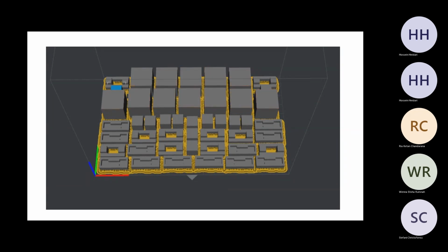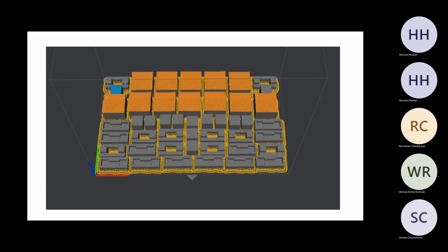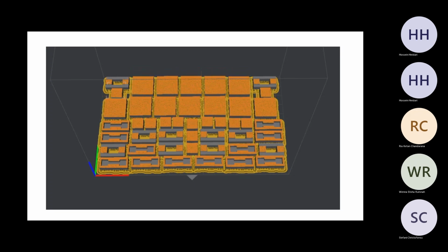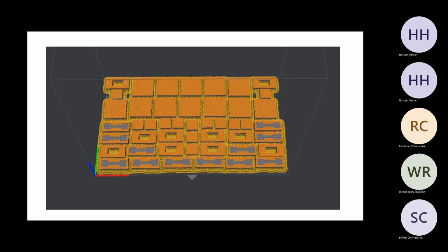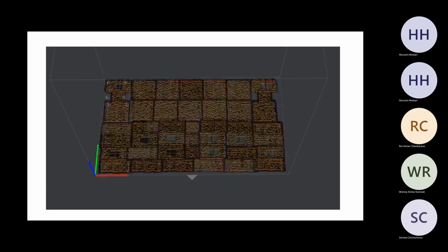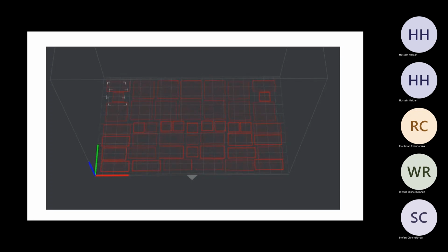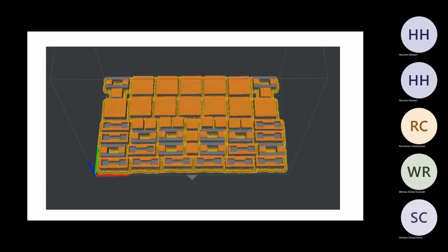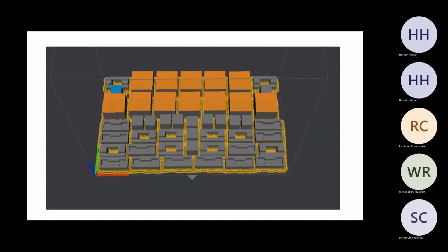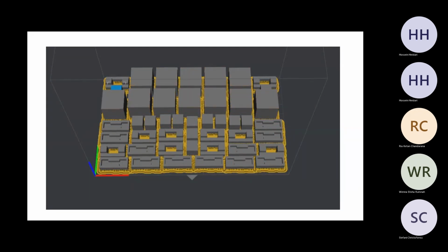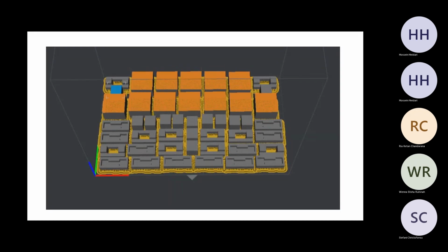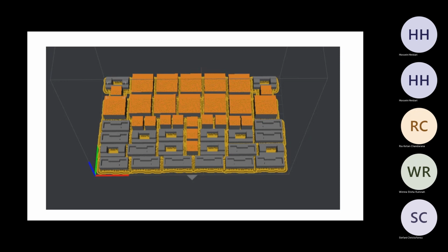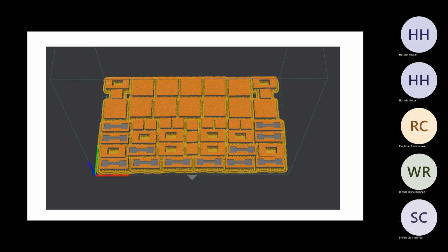Well, the thing is, do you guys know how these printers basically limit the penetration of light? They are designed so that they have an absorber in the resin, and that absorber doesn't allow the light to penetrate beyond the single layer that you're curing. If it does, then it's going to penetrate through and cure the other layers above, right? And you don't want that to happen. You don't want holes in the layers above to then be blocked and clogged because the light can penetrate all the way through, okay?